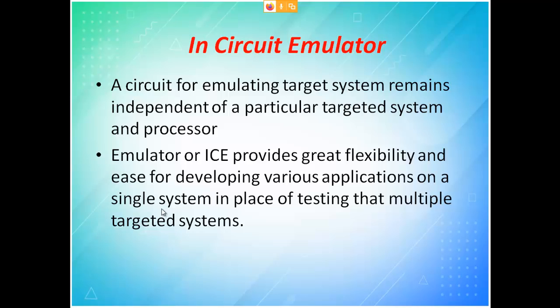So whatever type of input you want, you can get it from the in-circuit emulator. You don't have to go and purchase that particular type of equipment and then get the output. All such things are not required. If you want to sense temperature, there is no need to buy an LM35 IC, connect it to a controller, and get the pulse. This emulator will directly give the output that will be similar to the LM35. So that is what an emulator is.